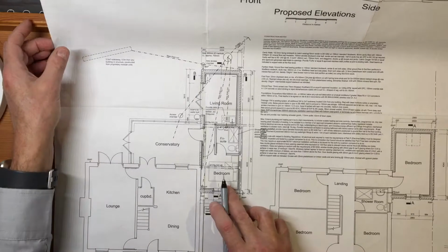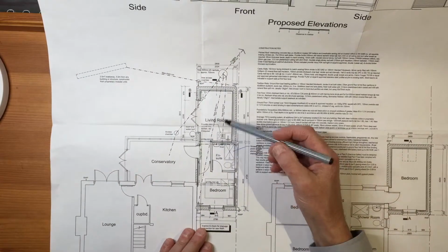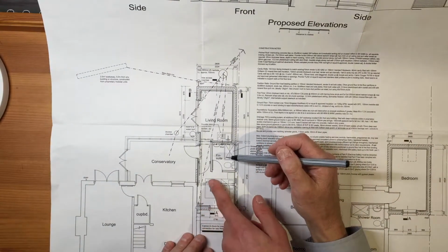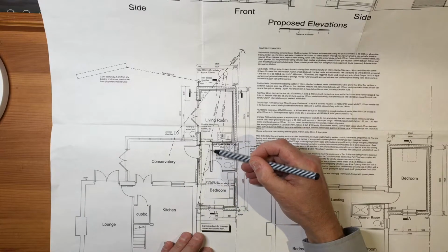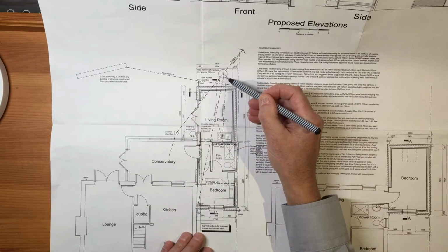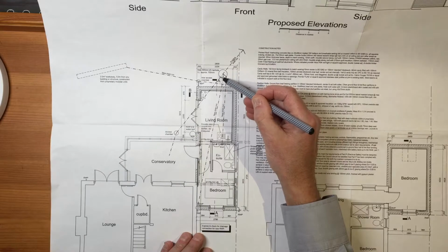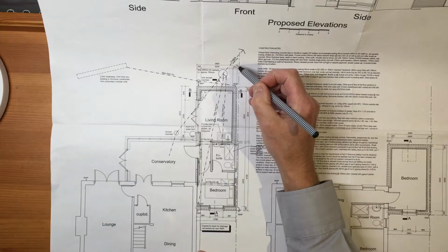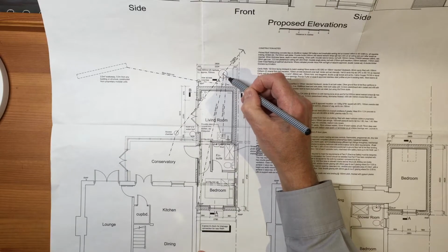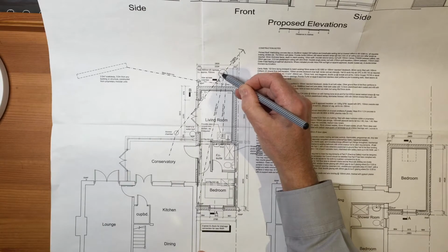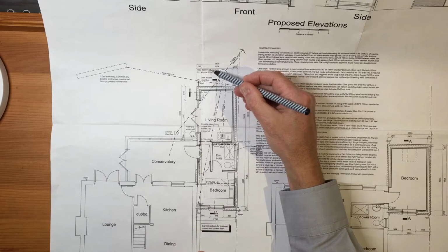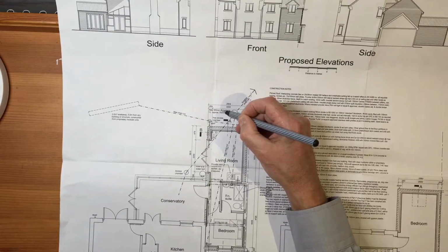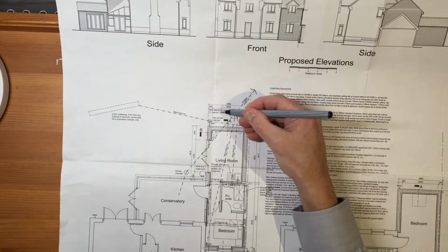Anything else? Point to anything else, Jake. What are those lines there? Yes, this shows the pipework under the foundation of the floor slab, all the way under, and it shows it running to, what do you think that is there? Maybe some sort of main supply of something? It is a drain, and it shows the drainage for the foul water, sewage water. And that is an access point, or what they call a manhole. And it says manhole there. 600mm diameter. And that's the symbol, if you can see that, guys, for diameter. It's a circle with a line through it.